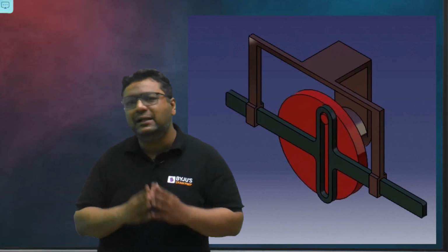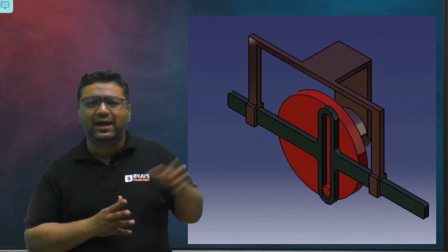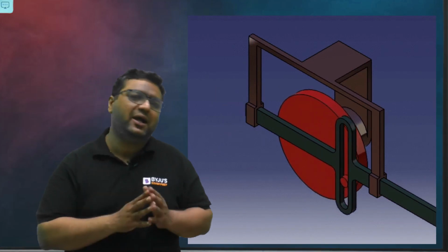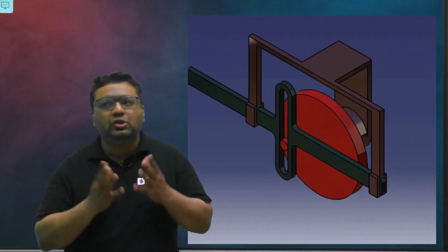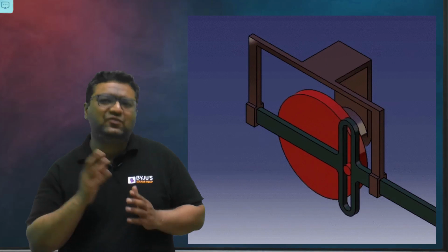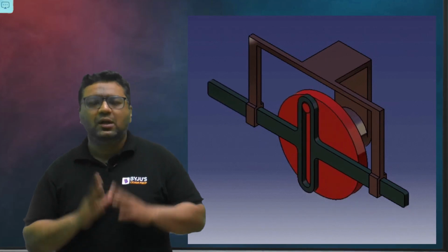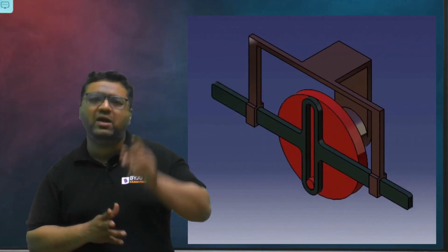If one slider gives us SHM in the horizontal direction, fixing the other slider gives the same SHM in the vertical direction. So the relative motion remains the same whether you fix the first slider or the second. That is why both sliders give us only one inversion.